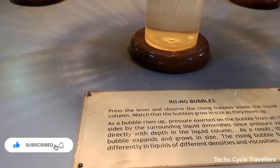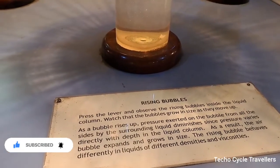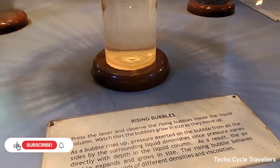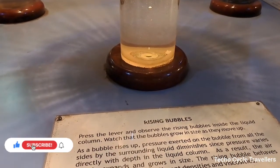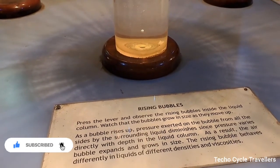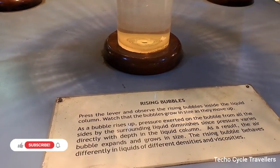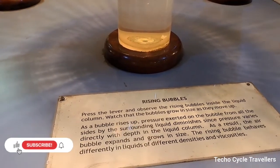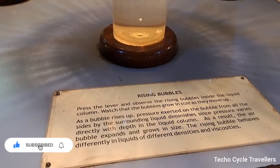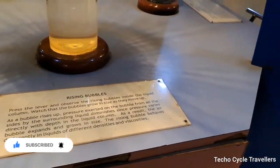Rising bubbles. Press the lever and observe the rising bubbles inside the liquid column. Watch the bubbles grow in size as they move up. As bubbles rise up, the pressure exerted on the bubbles from all sides by the surrounding liquid decreases. Pressure varies directly with depth in the liquid column, and as pressure drops, the bubbles grow in size. The rising bubbles behave differently with different densities and viscosities.